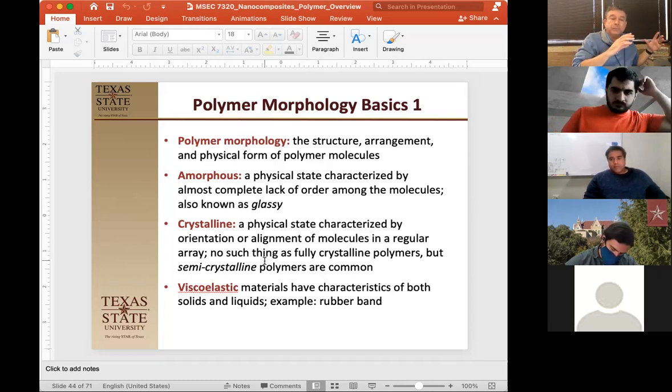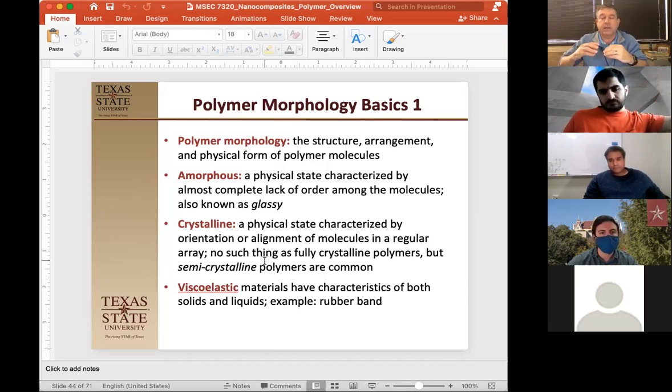In the exact opposite of that, let's say you have something where you can hydrogen bond or have a very easy periodicity. So these are stacked on these, which are stacked on these, and you have those going all the way through the system. That's considered to be a crystalline polymer. You have to have a regular arrangement of how they are stacked together.